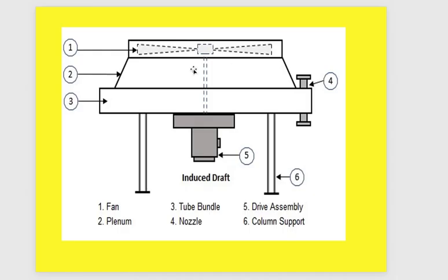So this type of structure is highly recommended in critical areas, for units related to conversion or something like that. Why? Because if you lose the power which moves this motor, the air will be directed naturally from bottom to top and you keep a little amount of your cooling capability.